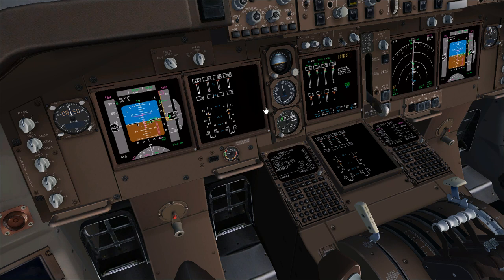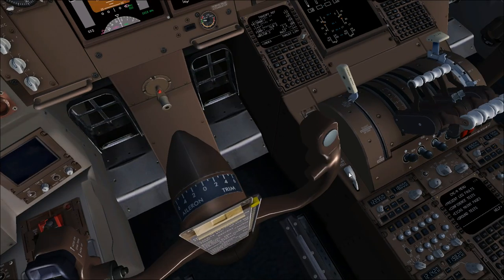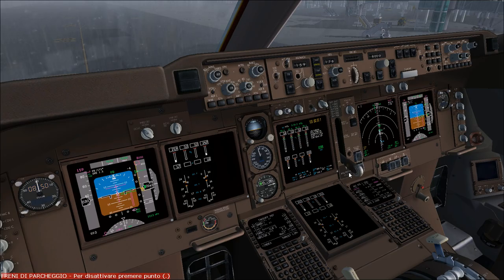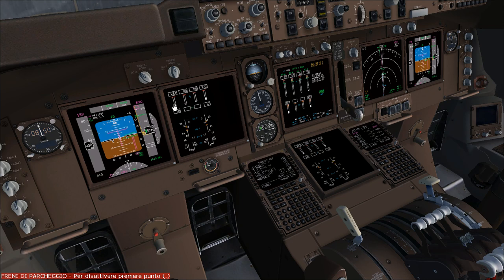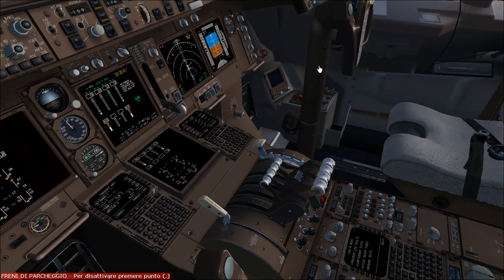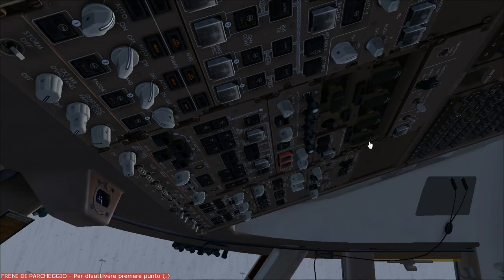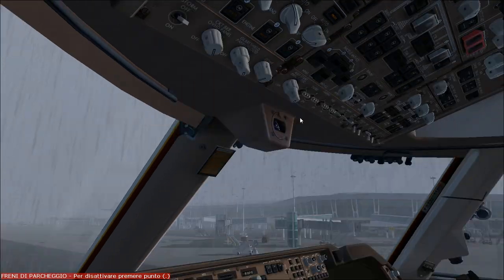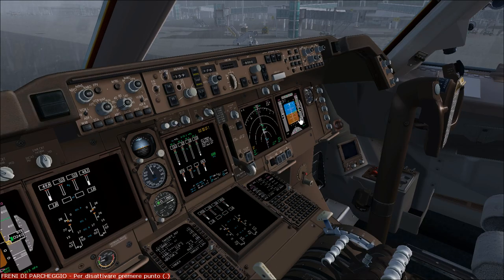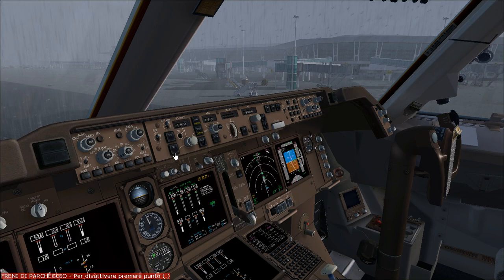Reset parking brakes. Okay, we finished the pushback, so we set the parking brakes. As you can see now, the engines are being started, N1 is rising, EGT is rising, and electrical generators 1 and 4 are off just because, as you know, they just come online when the speed of the generator is fine enough. The 2 button actually turns off because the engine is stabilized in a few seconds when they are okay. Now they are actually released.